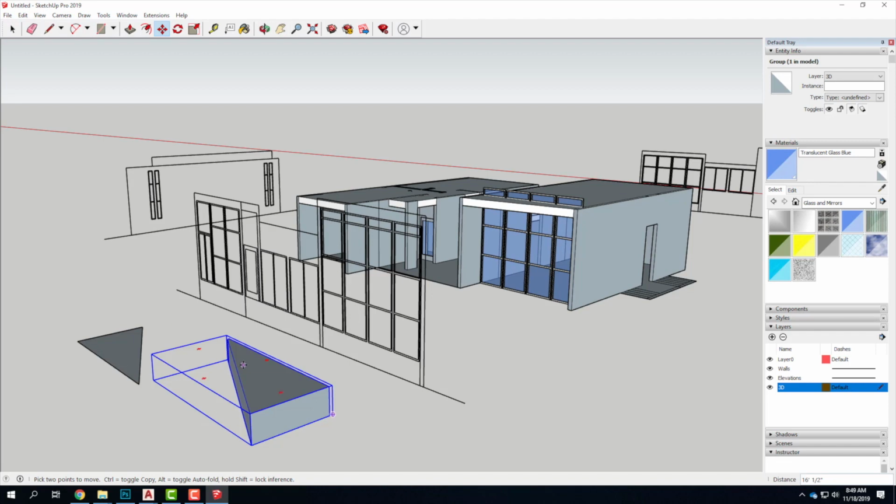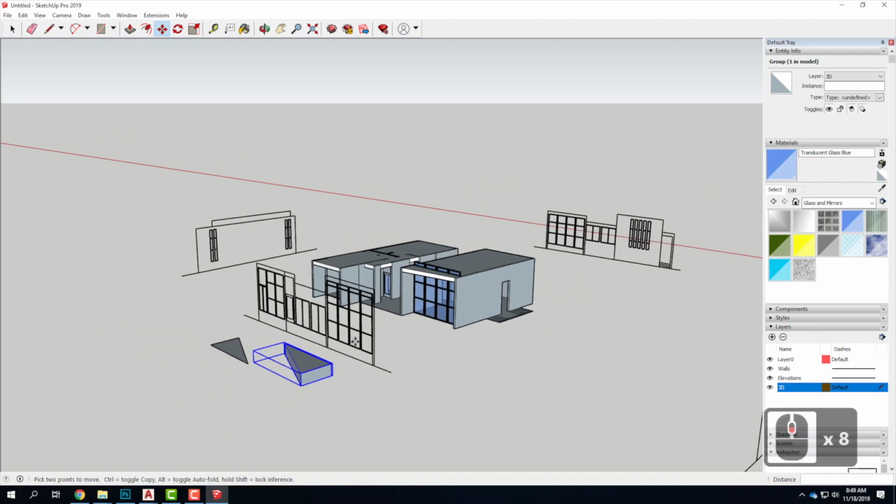All right, so I'm going to go ahead and let you guys start working. I don't want to keep using up all your time. Really, this is about modeling. I think most of you are pretty familiar with SketchUp and getting started. If you're not, it's okay. You will become pretty familiar with it pretty quick. There's not too many tools to worry about. Remember, delete the extra non-important AutoCAD layers. That's the most important thing you can take away with this: pare down your AutoCAD layers, start with the simplest group of lines that you can get, because it's going to end up being complicated if you don't.